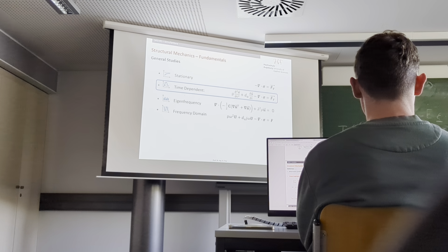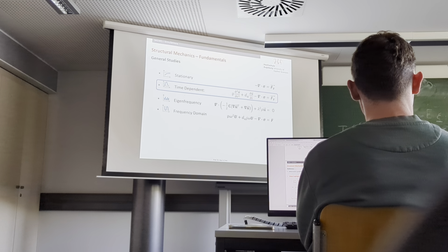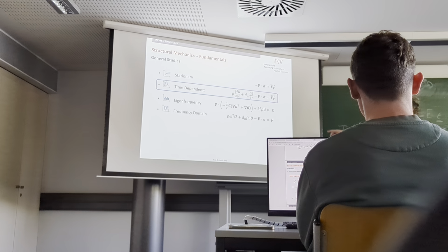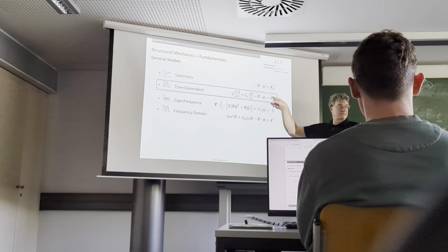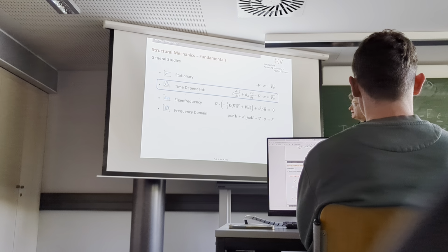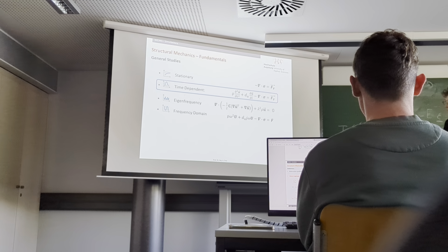Time transient simulation would mean we don't put a static force and then wonder what the stress and strain are in here, but make some time changing things. For example, by having time variant outside force or volume forces.